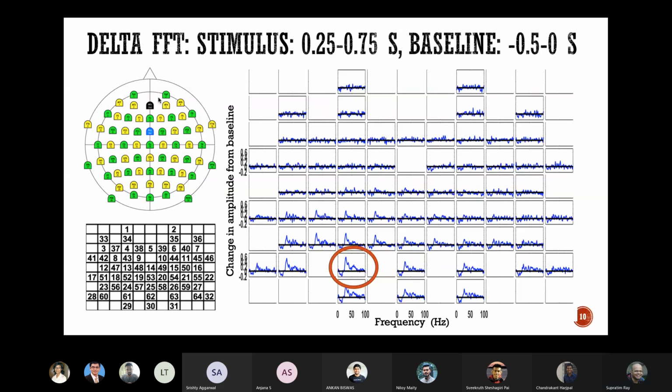When you have this reference electrode, or basically voltage, you have to have two terminals, and one is taken to be grounded, and this is taken to be zero. Otherwise, if you just leave it open, it will catch noise, and then your referencing and everything would be spoiled.